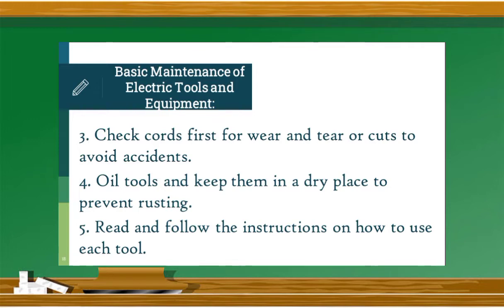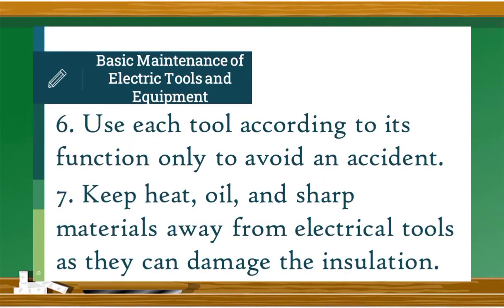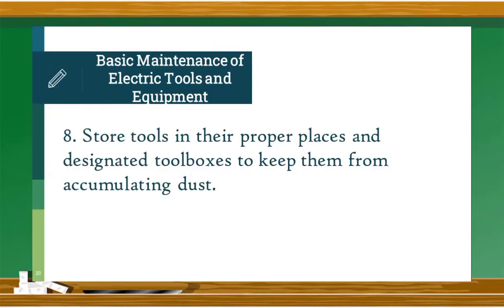to use each tool. Then use each tool according to its function only to avoid an accident. This is very important. And also keep heat, oil, and sharp materials away from electrical tools as they can damage the insulation. The last one, store tools in their proper places and designated toolboxes to keep them from accumulating dust.